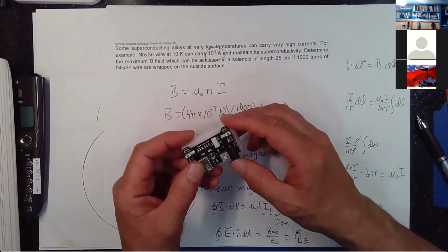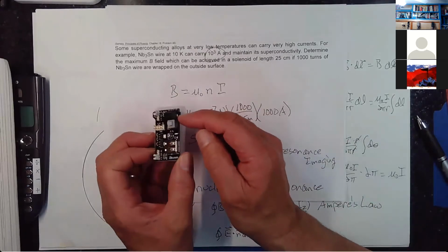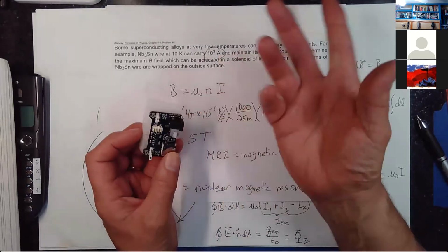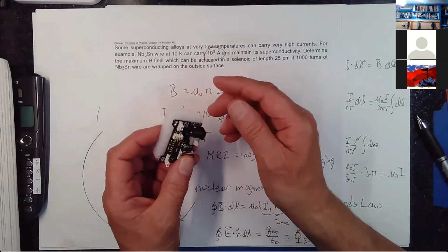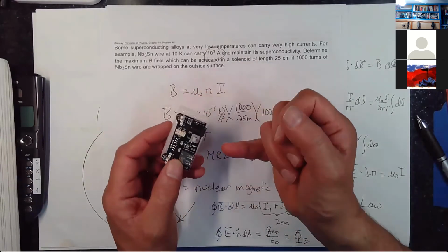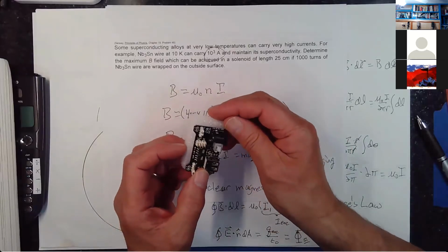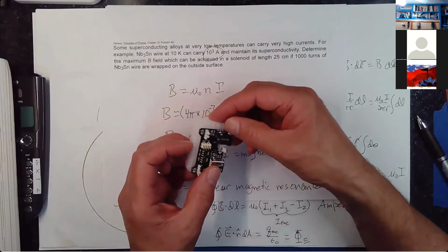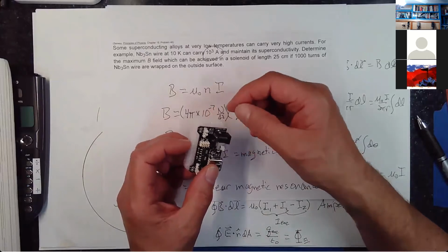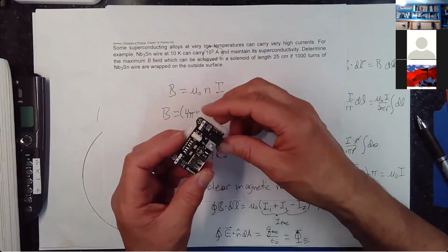If I was going to experiment much with this kit, I'd get a power supply that could just plug into here. It'd be what's referred to as a wall wart. It's a little transformer you plug into the wall, and it produces DC current that can then go into here. It says it can take 6.5 to 9 volts, so actually any little transformer that would do that.